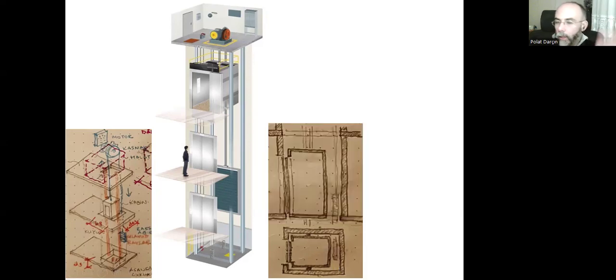The same thing, the same principle will be applied for the section, vertical section. We cut through the floor, and then there is this gap, hoistway gap, and the floor can go like that. There is the other floor. We cut through the cabin and its door, and there is this hoistway door on the floor and the wall, the upper part of the wall, and there is this wall at the back, and the counterweights, and we see the cables and everything. This is the section that we need to draw.